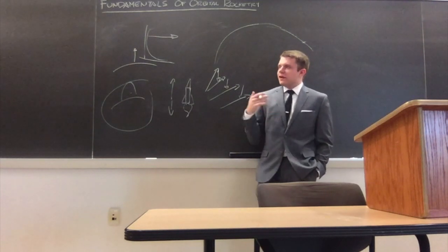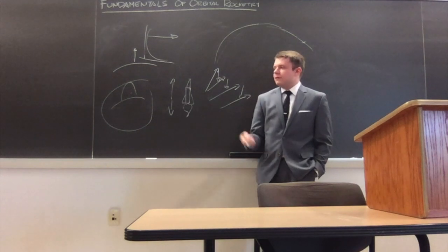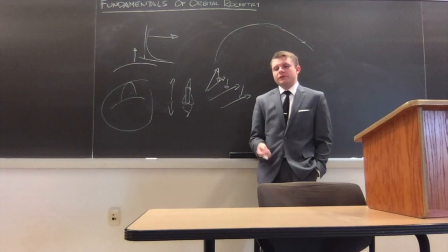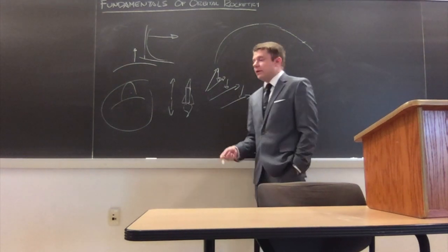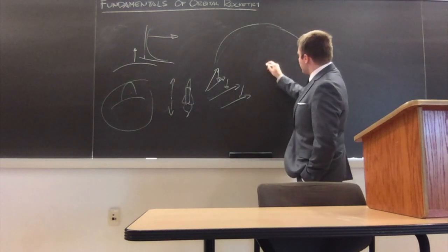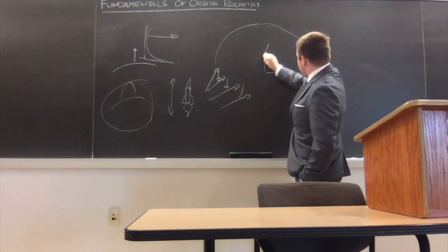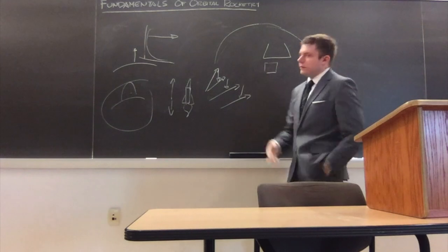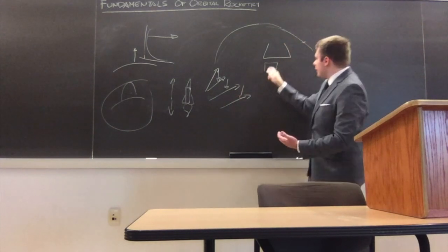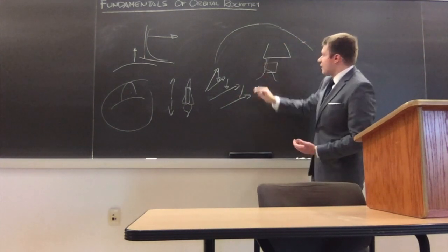So that's where you start talking about using vanes. The V2 rocket from the very end of World War II actually uses this, and some of the early American rockets use something like this, where you would have a rudder in the exhaust path of the engine, and you would steer the rudder to deflect the exhaust in whatever direction you need to control it.